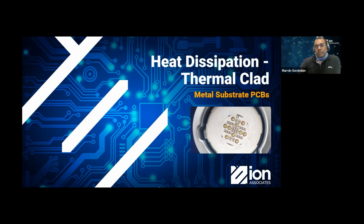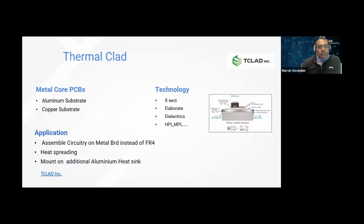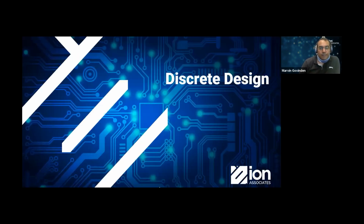And just to build on that, depending on the application, depending on the power that you're generating, you generate heat. So we have options for dissipating that heat. We have thermoclad. So here, if you have a circuit that's getting hot, you might want to distribute that heat away. So we have aluminum substrates, copper substrates. We can assemble the circuitry on the metal board instead of FR4. We spread the heat away, and additionally, we can mount that on an aluminum heatsink. So it's a material we can use to help dissipate the power, even for low power applications, but up to high power applications, to help extract heat from our circuits and increase that reliability.